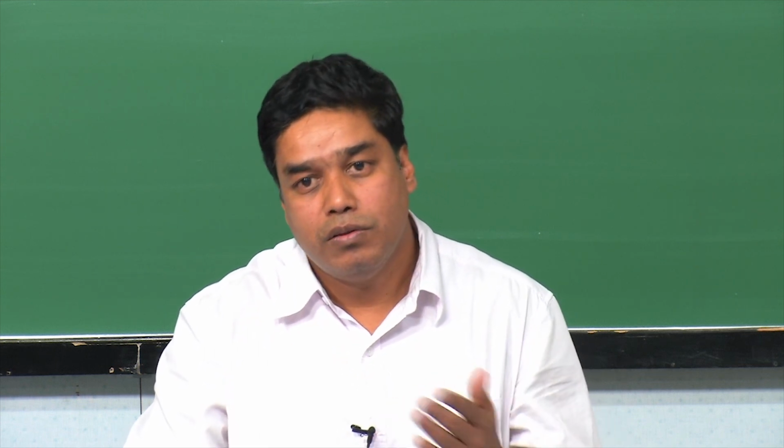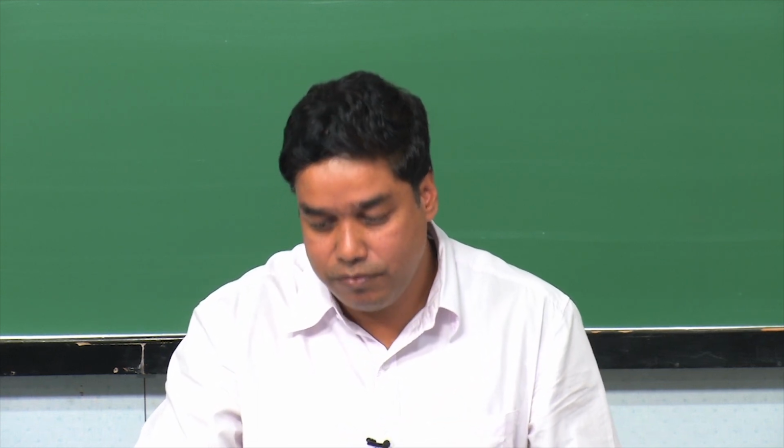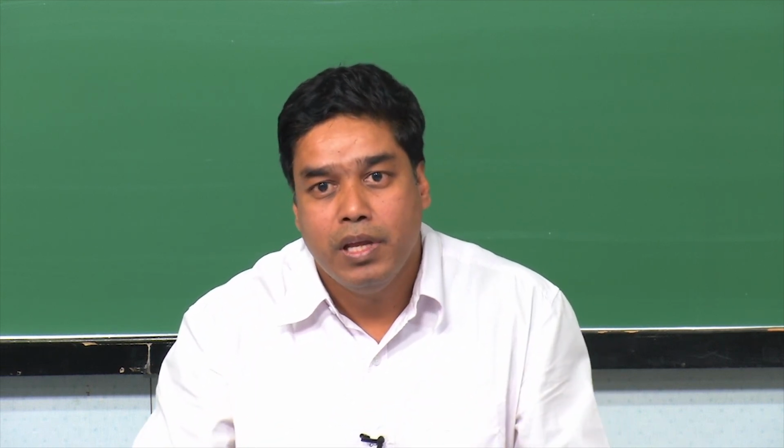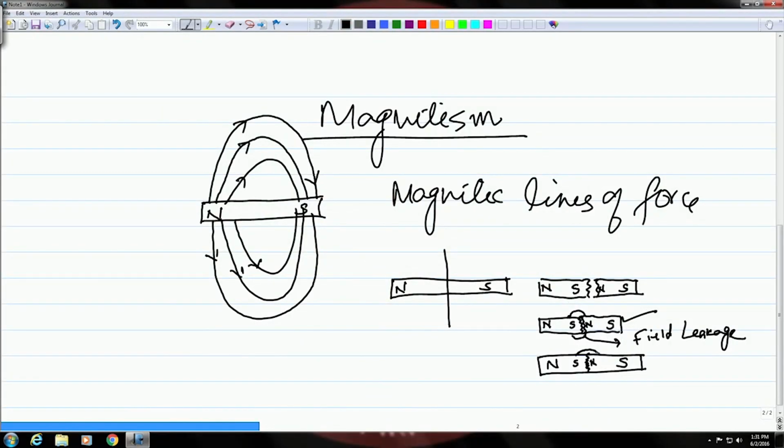It will create its own magnetic field, a tiny magnet, and if you now apply magnetic particles on this surface, the particles will be attracted to this crack, and that is how it will make visible indications of the crack.